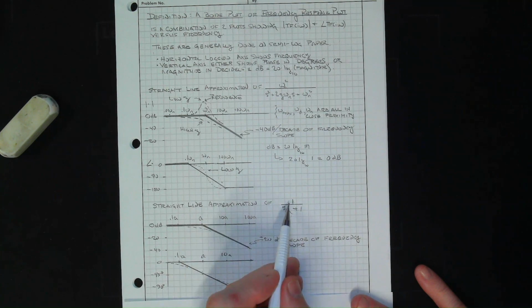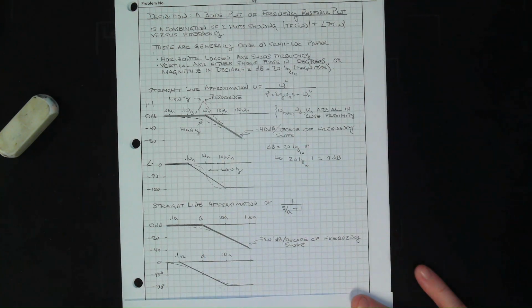So what do we notice here? For every power of s, there's a 20 dB shift in gain at high frequency. At low frequency, it stays flattened, but at high frequency, you're losing. Okay, and for every power of s, we lose 90 degrees. Or if it's a 0, we add 90 degrees. Okay, now when you look at this, what does this show? Both of these would be called low-pass systems. So at low frequency, the strength of the signal goes through. Whatever the amplitude was, the gain in the system is 0 dB or a factor of 1.